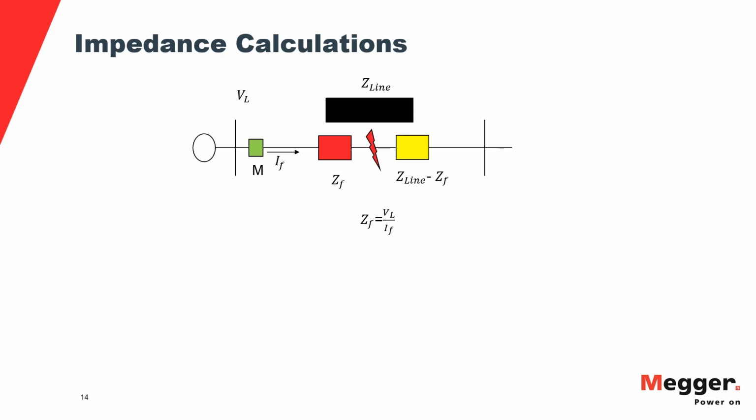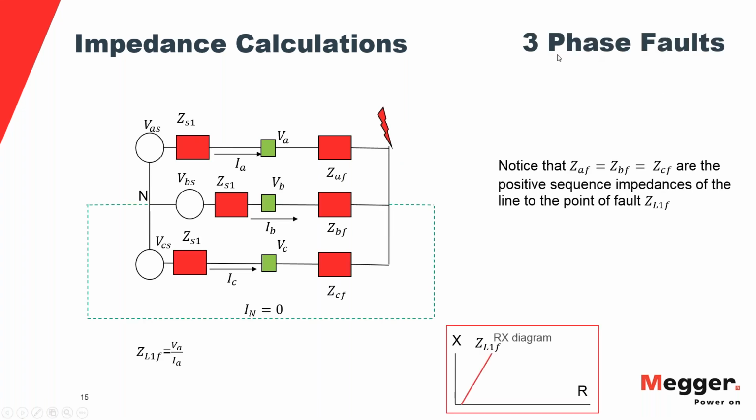are calculated. For instance, for a three-phase fault, if we say that the fault happens at some point in the line where the three phases are bolted together, so essentially the voltage here is zero. If the system is balanced, then we can consider this point to be the neutral. And since it is a three-phase fault, the current through the neutral is going to be zero.